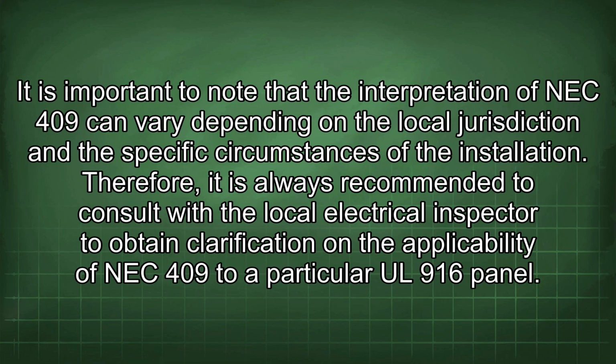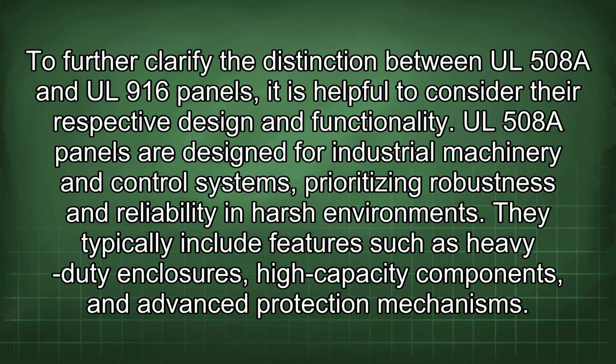It is important to note that the interpretation of NEC 409 can vary depending on the local jurisdiction and the specific circumstances of the installation. Therefore, it is always recommended to consult with the local electrical inspector to obtain clarification on the applicability of NEC 409 to a particular UL 916 panel. To further clarify the distinction between UL 508 and UL 916 panels, it is helpful to consider their respective design and functionality.